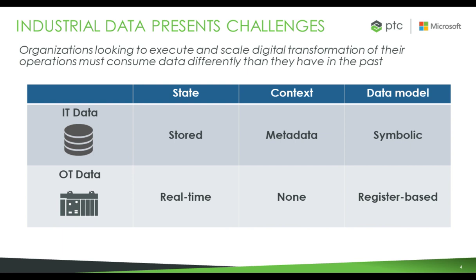And I think the best example of this is with the Modbus protocol, which is really used everywhere. It's present in most facilities or production environments. And with Modbus, you really have to know the data type going in order to read the correct registers. And we'll go into that a little bit more, but we haven't even started to talk about what others think of in terms of context of data, just in terms of, this Boolean represents whether or not this machine is on or off, that machine is on this line, which makes this kind of parts, which are part of this type of products. You're not even getting into that piece of it.